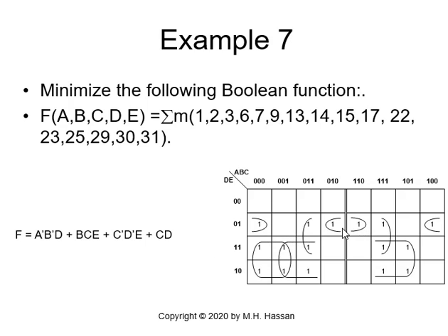those groups of 2, those groups of 2. So we have those ones. If you look, this one with this one, with this one, with this one is really a group of 4. We can simplify this group of 2 because I have another group of 2 that I did not see here. So the 1 will cancel with the 0 for the A, and the B will cancel with the 0 again.